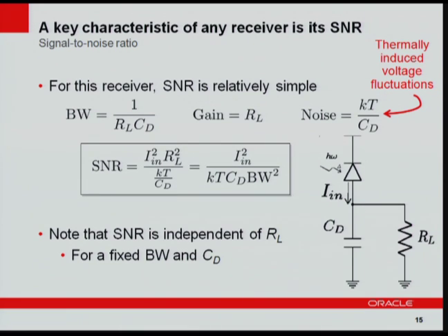has very little room to play, pretty much, because the CD is fixed by the parasitics of what connects in between your photodetector and your other substrate, and the bandwidth is what you desire. So this equation is what I want to imprint on your minds: there are very fundamental trade-offs here. That is, if I want to increase my bandwidth by a factor of 2, I either have to decrease this capacitance by a factor of 4 or increase the current by a factor of 2.